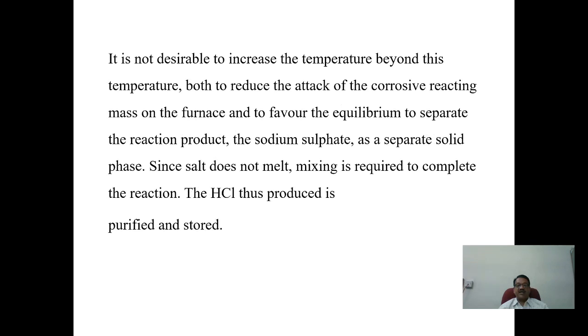It is not desirable to increase the temperature beyond 400 degrees centigrade, both to reduce the attack of the corrosive reacting mass on the furnace and to favor the equilibrium to separate the reaction products, the sodium sulfate, as a separate solid phase. Since salt does not melt, mixing is required to complete the reaction.